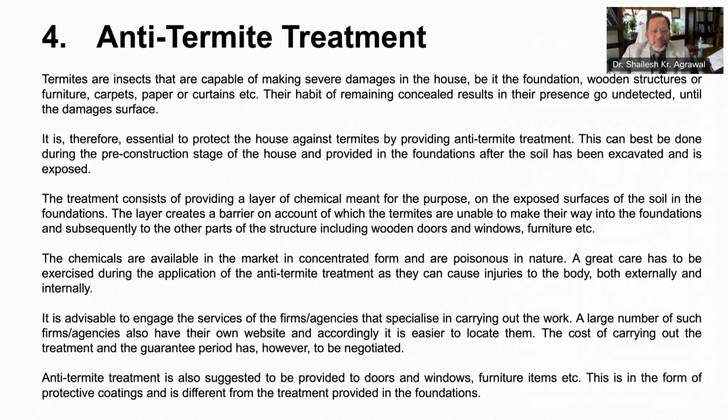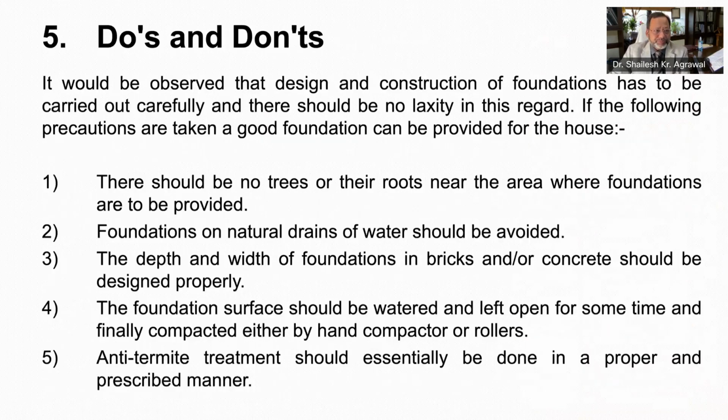But before I sign off, let me give you do's and don'ts for design and construction of foundation. There should not be any tree or their roots near the area where foundations are to be provided. Foundations on natural drains of water should be avoided. The depth and width of foundations in brick or in concrete should be designed properly. The foundation surface should be watered and left open for some time and finally compacted either by hand compactors or rollers. Anti-termite treatment, as I explained earlier, should essentially be done in a proper and prescribed manner.